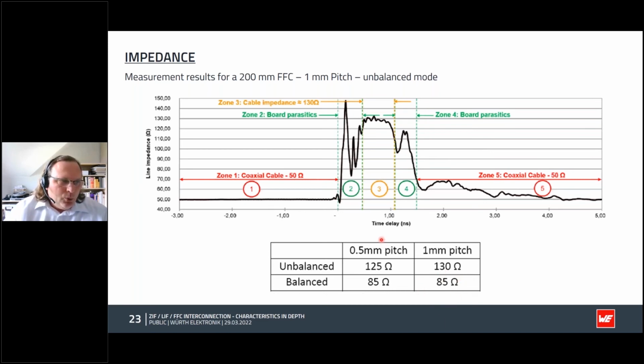In zone 2 and 4, here and here, the impedance is unstable. Reasons for this are SMA junctions and ZIF connectors that cause noise and make the measurement unstable. The protective film of the measured cable consists of PET of different thickness and colors, therefore different impedance.